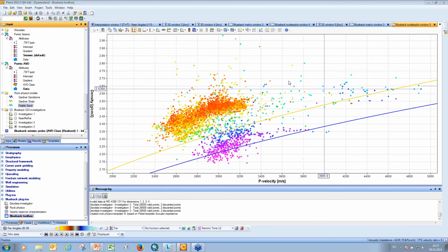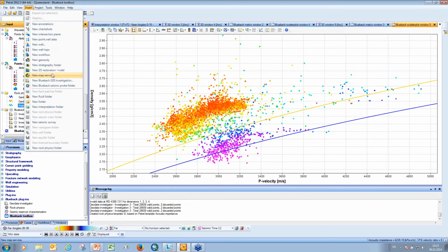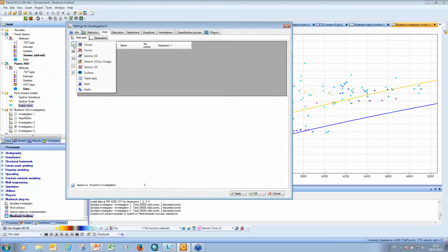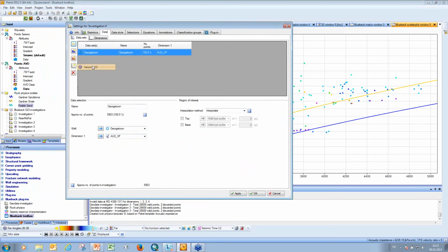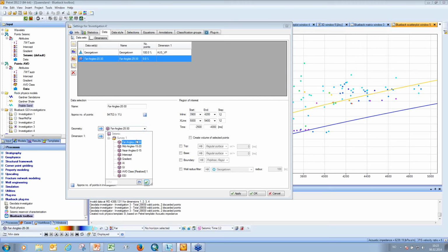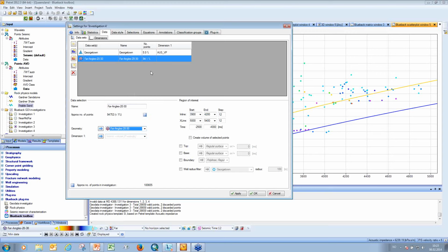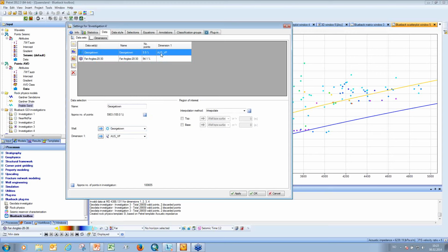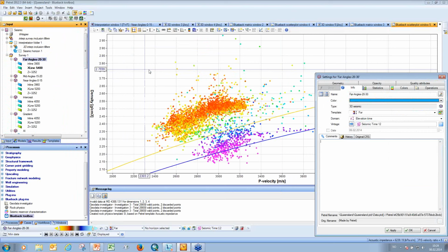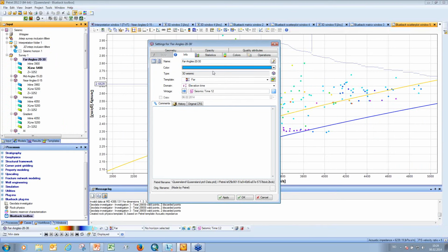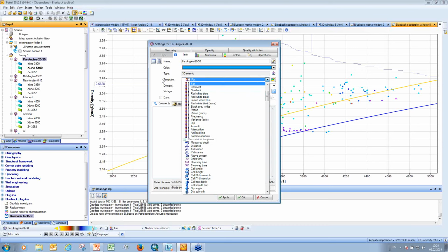Is it possible to cross-plot wells together with seismic data? Yes, that's possible. Inside of the GDI, we can add, say for example, a well with VP and then seismic if we have it with the same property. So in order to do plotting of seismic and wells together, you need to have data of the same dimension inside of Petrel. And that's fairly easy to do with your seismic. You need to simply assign the correct Petrel template here.